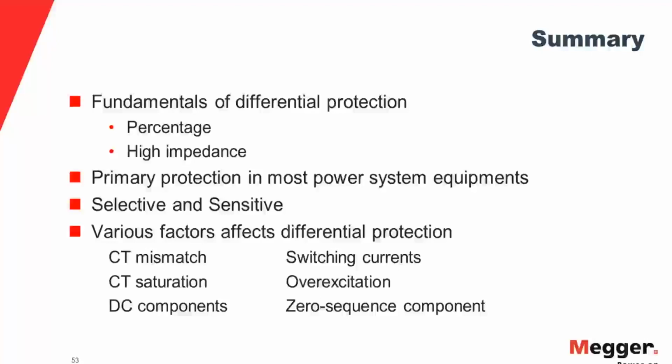Along with that, a very important thing here is you have centralized control when you daisy chain multiple units. You can daisy chain up to 32 current channels. If you want to do a scheme test on a bus differential which involves about 6 feeders, you need 18 currents to test. So you can daisy chain up to 32 channels to test your bus differential scheme.